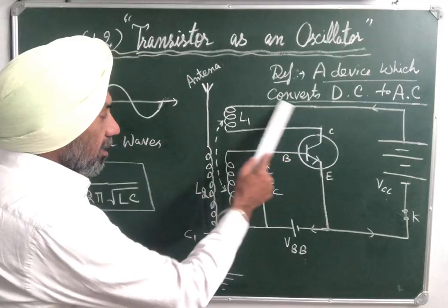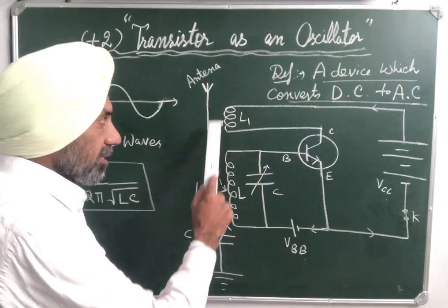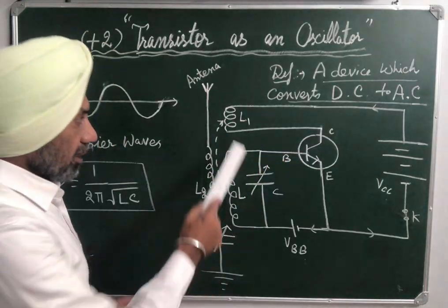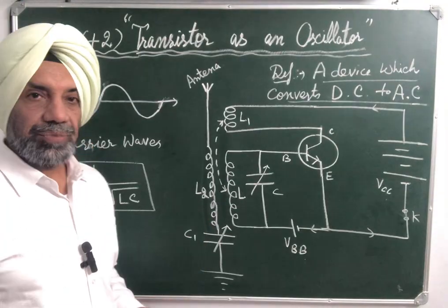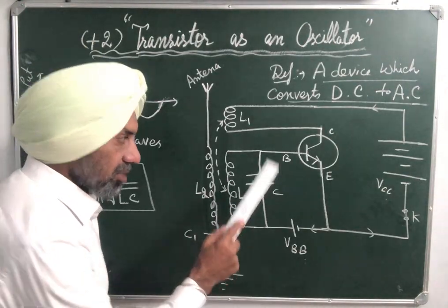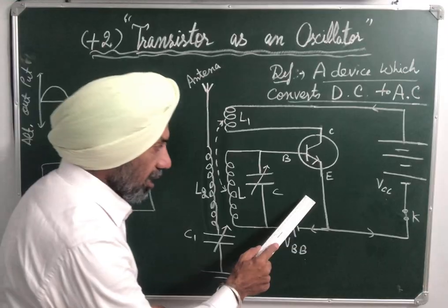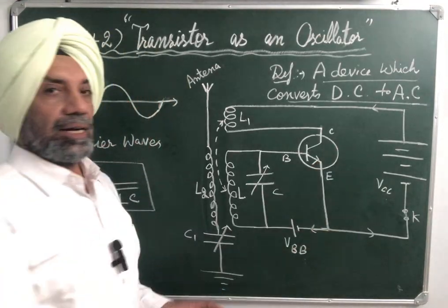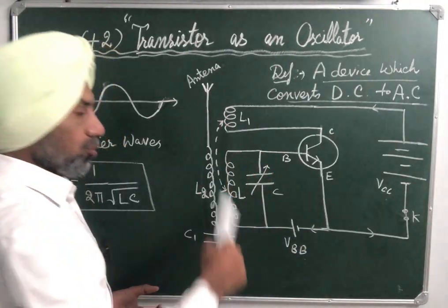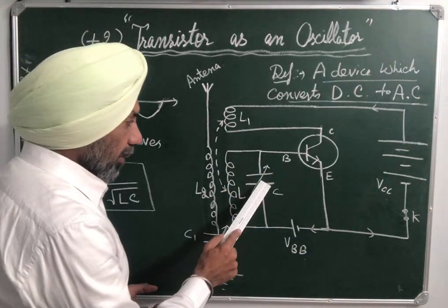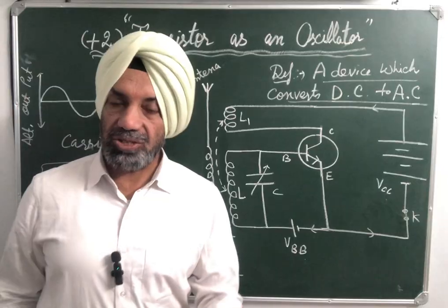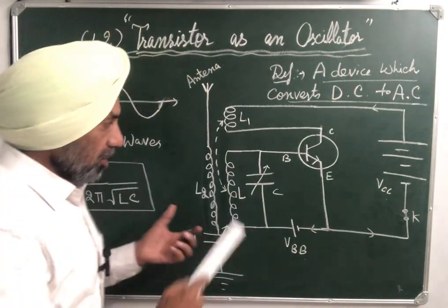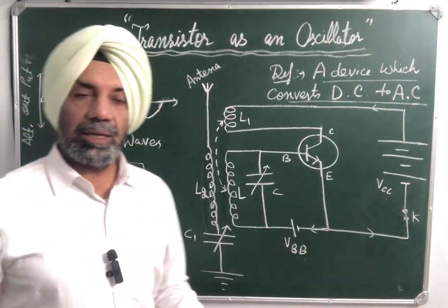Hence decreasing magnetic flux is linked with L1, which further decreases the flux through L and further discharges the capacitor C, further decreases the forward bias, the emitter current and the collector current. This process continues till the capacitor is fully discharged, and this process is repeated again and again.